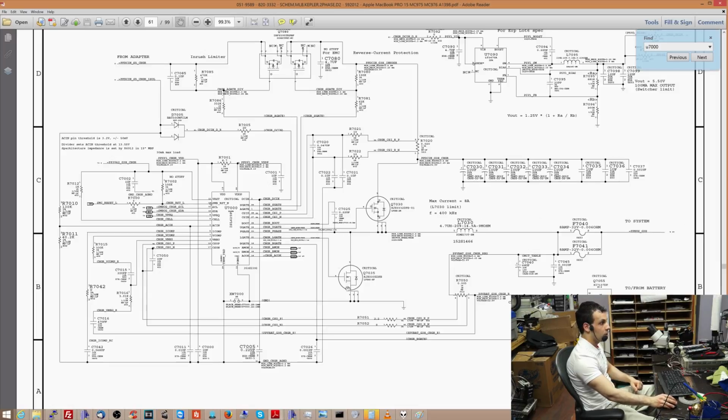It's never going to make it over here because there is 0 ohm resistance to ground on this transistor. So a short is pretty much anywhere in the circuit where the power itself stops. It's stopping it, and it's keeping it from going where it's supposed to go. And most of the time that is occurring because of a short to ground. You could also have a short over here where, let's say, this transistor simply died, so it's not even shorted to ground, it's just not opening. That could be a short.